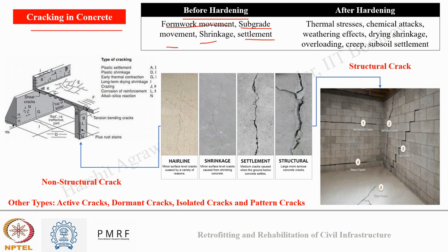And it can happen after concrete hardens due to several reasons like thermal stresses, chemical attack, weathering action, drying and shrinkage, overloading, creep, subsoil settlement. Any of these can be the reason. Okay. Now, the cracks in concrete can be classified into two categories: structural crack and non-structural crack.